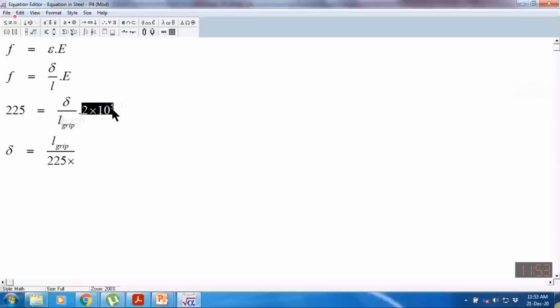So it means that if I know the grip, which will be equal to the thickness of both plates, and I'm using this A325M bolt whose diameter is equal to 25 mm, and I want to produce the 225 kilonewton pre-tensioning, I compute it by this formula because this is made of steel.